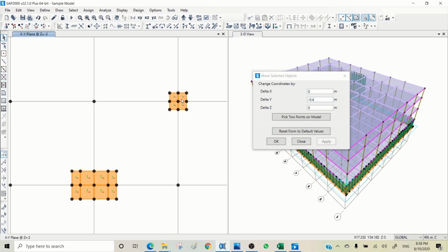What will define the thickness of the pile cap, because there is no bending or shear here, is just a matter of having enough depth to meet the requirement of the development lengths of the bars, under tension or compression, depends on the type of load. If the column is fully under compression, you just need to maintain the development length of the bar under compression. If it's under significant bending moment, you need to have enough depth to have the actual embedment depth for bar under compression, full tensile capacity.